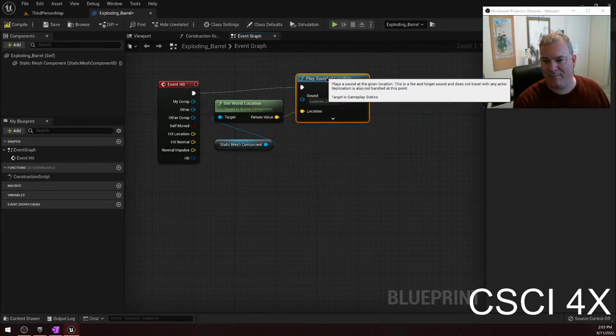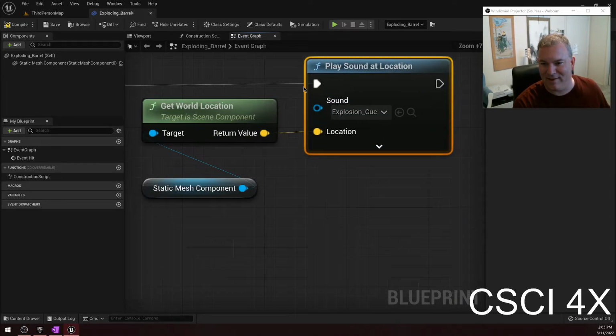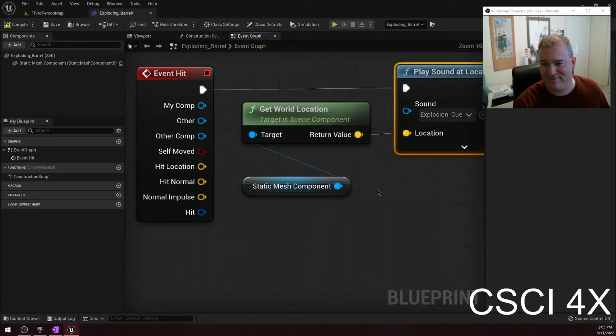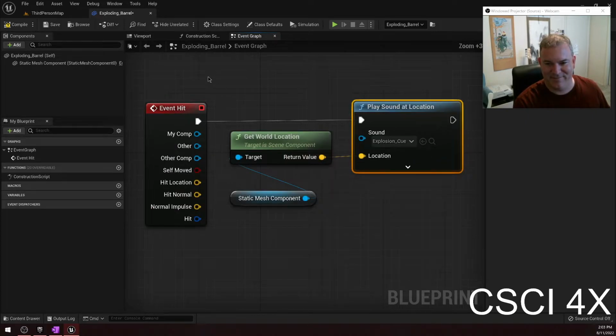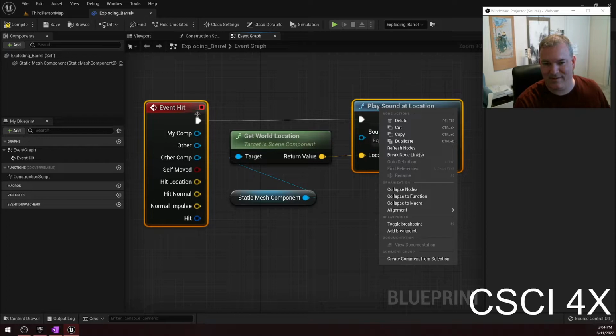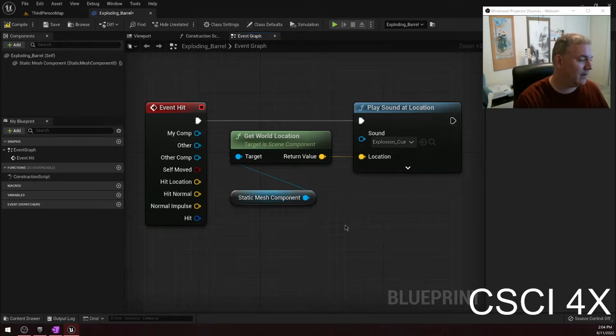Because it'll snap to grid, but a lot of times, if you look at this, when it snaps to grid it's very slightly off. I don't know if you can see that, but it's that far apart there and that far apart there. So if you select them, you can go to straighten connection, or you can select them and hit Q. I do that a lot.